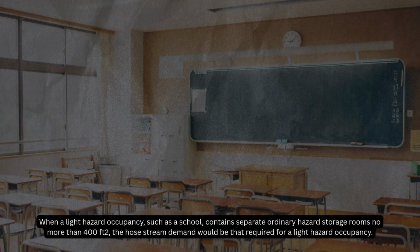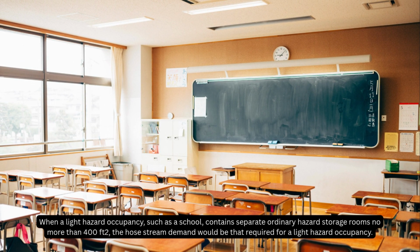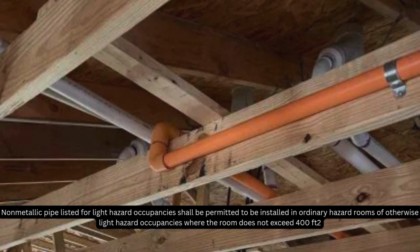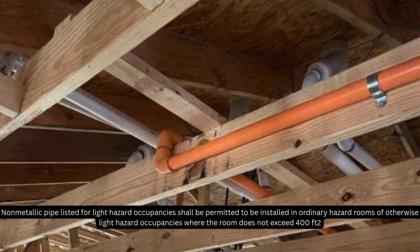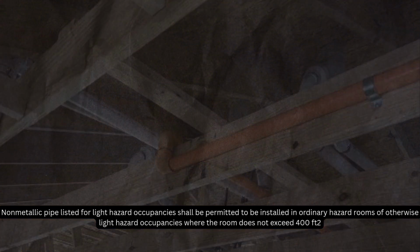Unused attics. When a light hazard occupancy, such as a school, contains separate ordinary hazard storage rooms no more than 400 square feet, the hose stream demand would be that required for a light hazard occupancy. Non-metallic pipe listed for light hazard occupancies shall be permitted to be installed in ordinary hazard rooms of otherwise light hazard occupancies where the room does not exceed 400 square feet.